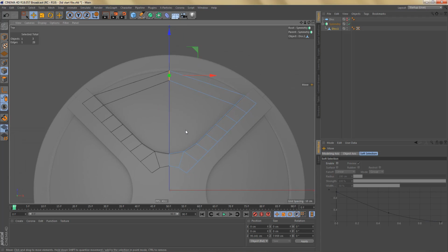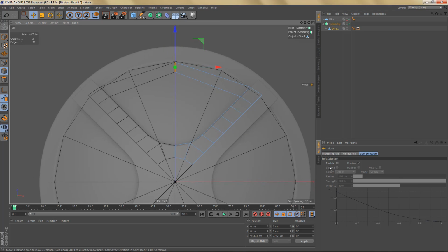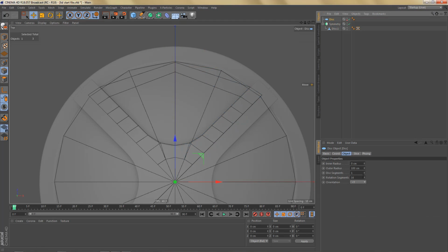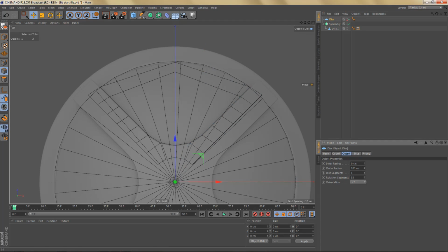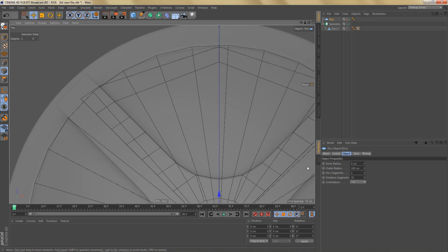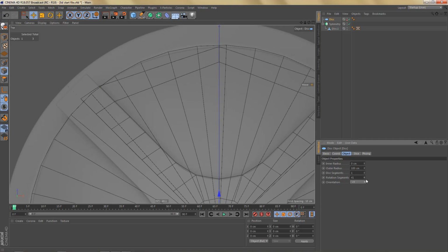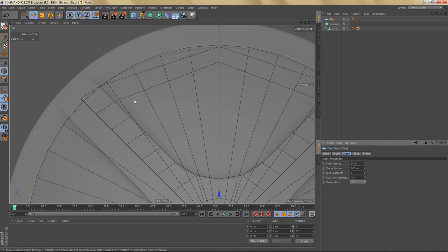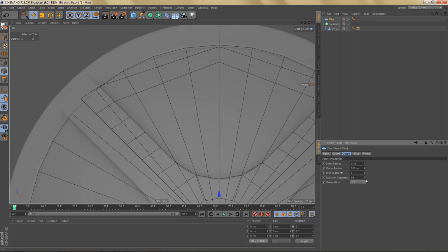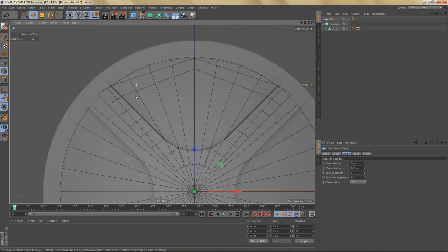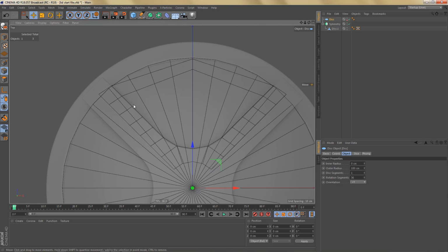And then I'm going to use the helper disk that I have here. Let's go ahead and increase the rotation segments to something that more or less matches the edges here. It's not going to be super precise or anything, but something like this should do. Maybe we can bring this back down to 36. So I think I want 4 segments here, and that's going to be fine.